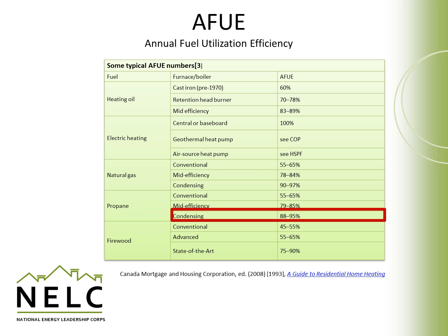Similarly with propane, these types of furnaces have very little heat loss in their exhaust. The exhaust is not a high temperature exhaust, and in the process of combustion, some water vapor tends to develop, and that's why they call them condensing furnaces, because we often have to catch the condensate out of the exhaust pipe from these furnaces.